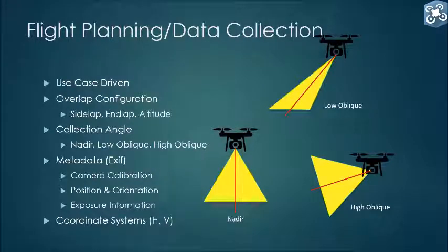Just a little bit more in relation to your flight planning. This is a use case driven task in essence. These uses will be discussed on the next slide, so you'll understand what I mean when I say use case driven. The use determines your angle of capture, for example, whether that's nadir, low oblique, or high oblique.